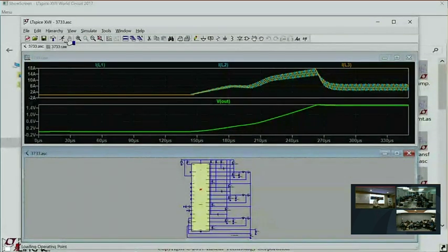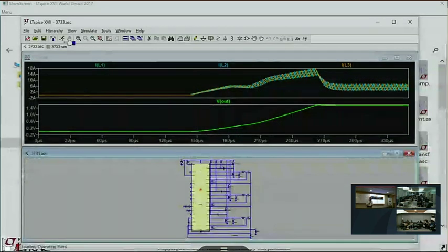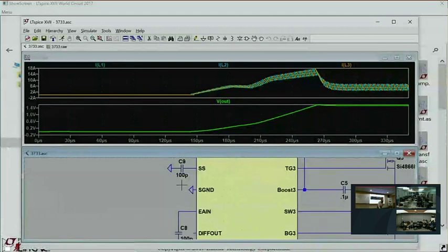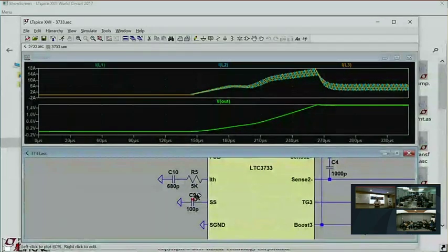However, the jig circuits are not reference designs, okay? The jig circuits are made to quickly show you the behavior of the controller, but they're not reference designs because they're made to simulate fast, not be good circuits. Now, there's usually an error in the circuit that makes it simulate very fast, but also makes it entirely impractical. What's done here is the soft start cap is very small. Now, a current mode controller doesn't actually need a soft start. It can just work at its own current limit, be happy, and start up.